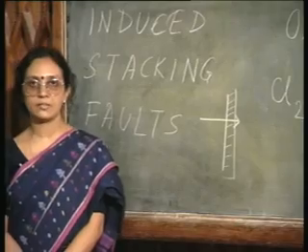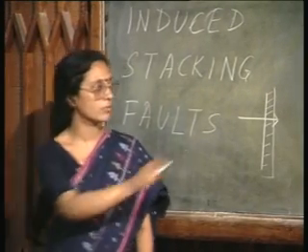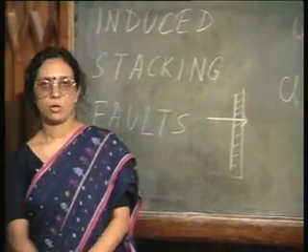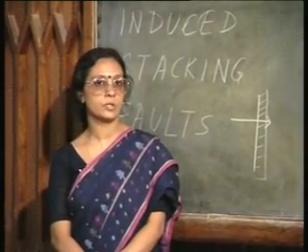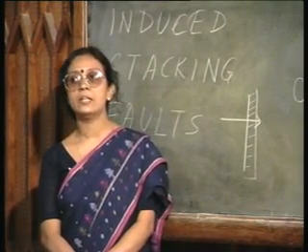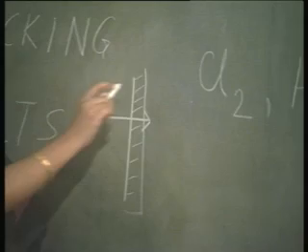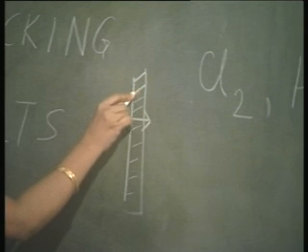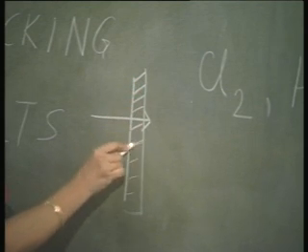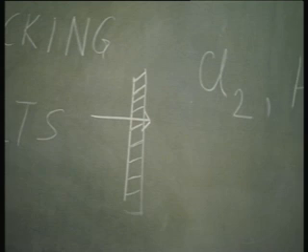Now, what is there at the interface? To begin with, it had a lot of silicon-silicon bonds, because it was part of the silicon crystal lattice with all the silicon-silicon tetrahedral bonds. Now, these silicon-silicon bonds are breaking and new bonds are forming between silicon and oxygen. But since this interface is the last region to be oxidized, there is a possibility that even though the silicon-silicon bonds are broken, they still have not found time to react with oxygen to form new bonds.